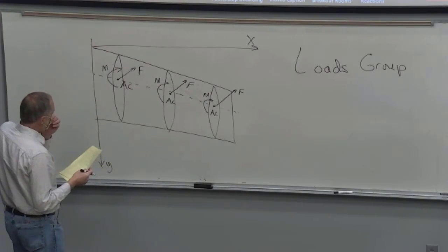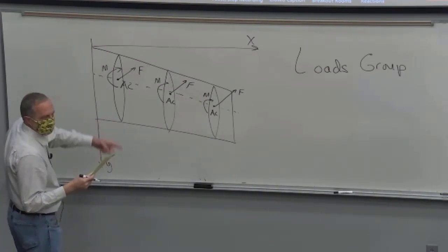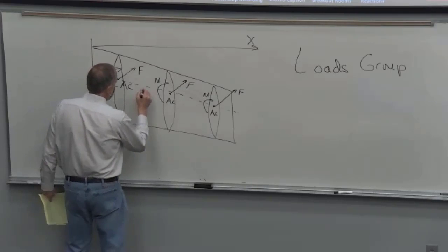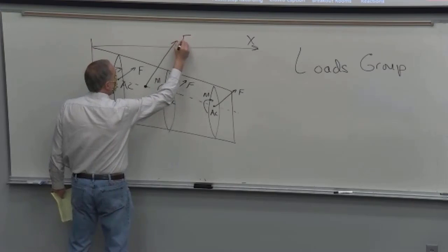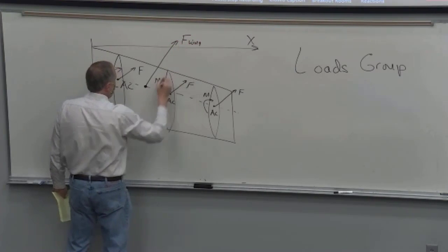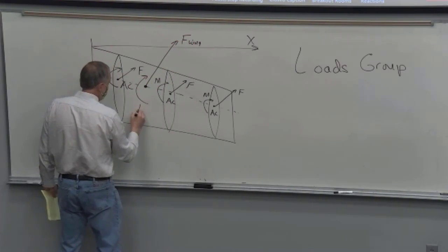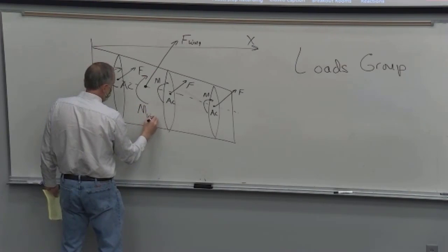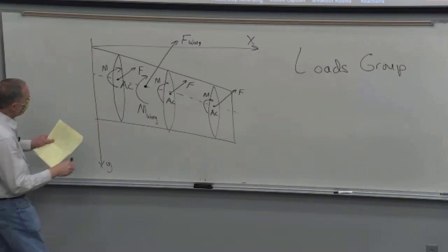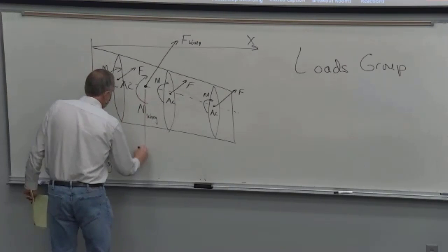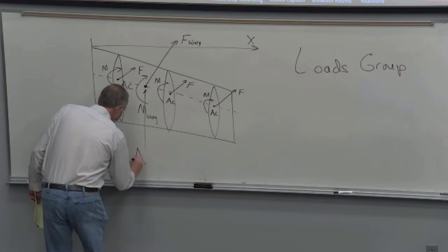So what we want to do is resolve that distributed load into a force for the whole wing and a pure couple for the wing. And the point at which that acts is the aerodynamic center for the wing.